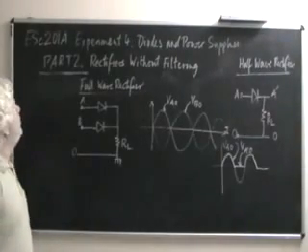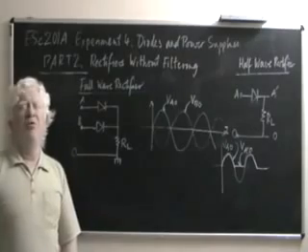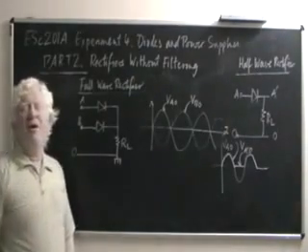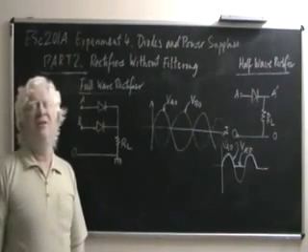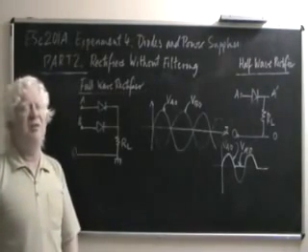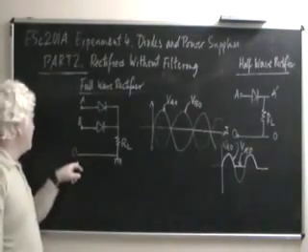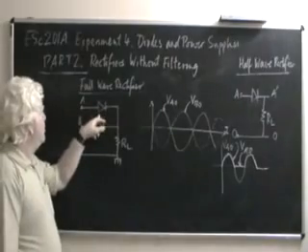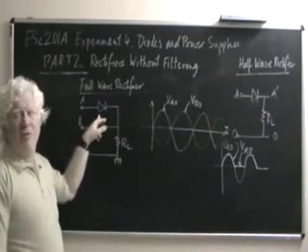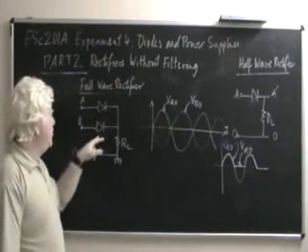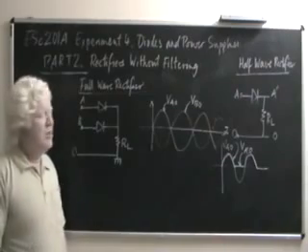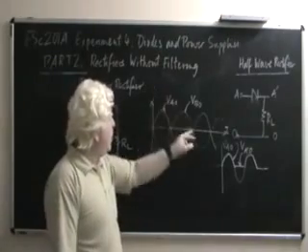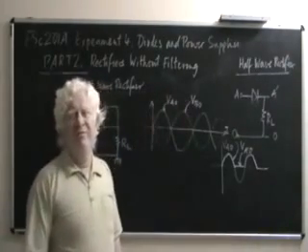So we now come to the full wave rectifier, as I was about to introduce you to it. You see, a full wave rectifier makes use of both terminals of the secondary side of the transformer, both the extreme terminals. O is of course used as the return path. So you put a diode on A, like we did before. We also put another diode on B. Now let's go over to this waveform diagram and see the waveforms VAO and VBO.